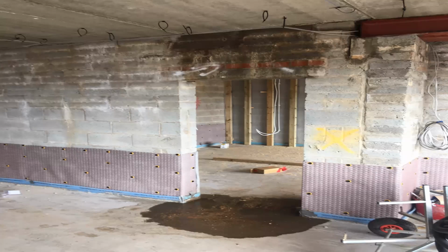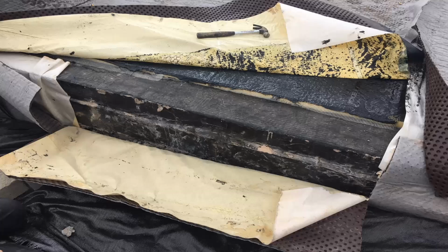Well, there's your defect. Okay, so you go to the edge of the deck. We exposed the waterproofing to see what was going on, and we can see at the edge of the deck there's a cheap grade insulation which was used, which is kind of compressible and not appropriate to support a waterproofing product. Okay, there was a much more robust insulation specified, so that's corner cutting. That's the client trying to get value. We'll just put this stuff in, it's good. Well, it's not.